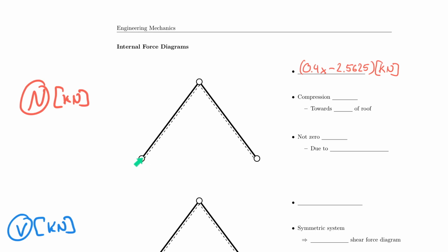Again, here, if I plug in 0, I will actually end up with negative 2.5 something. So what is a negative again? A negative means the side of the dashed fiber or the reference fiber, and it's actually going to be down here. Notice that this here is a right angle. I will not show this in the future again, but that's important to understand. It's not like a line's random, it's actually perpendicular to that.